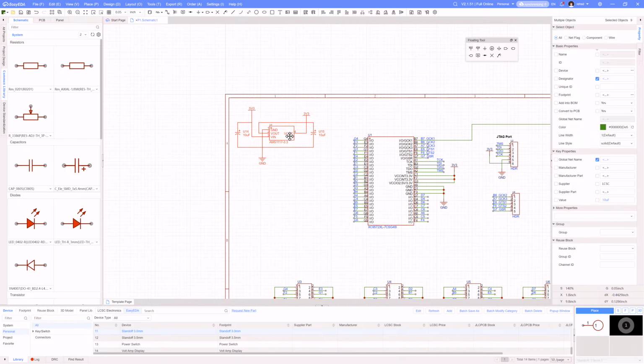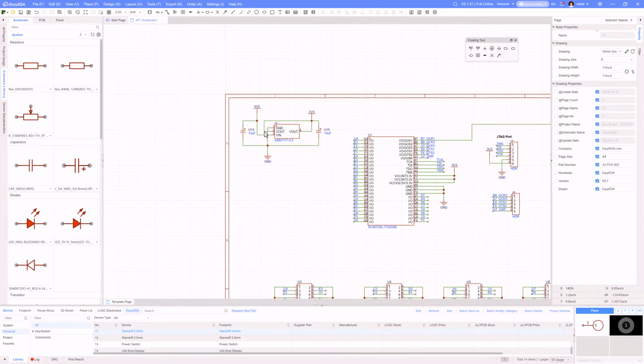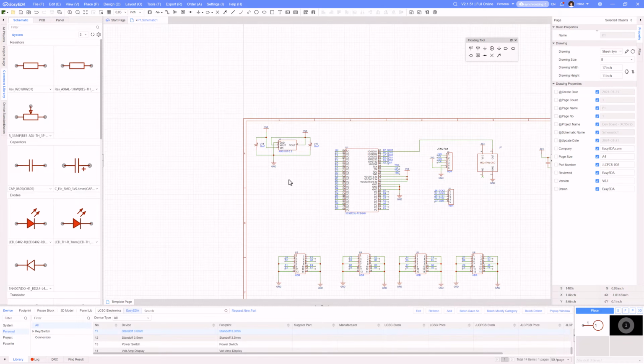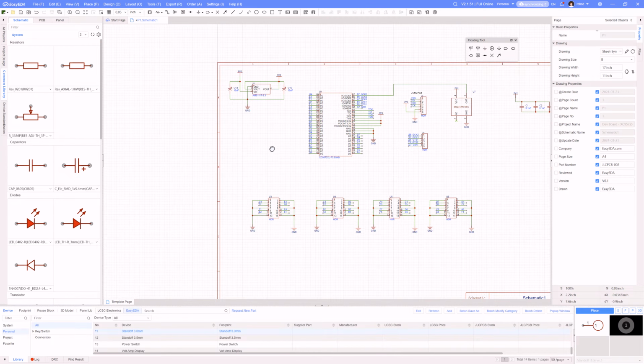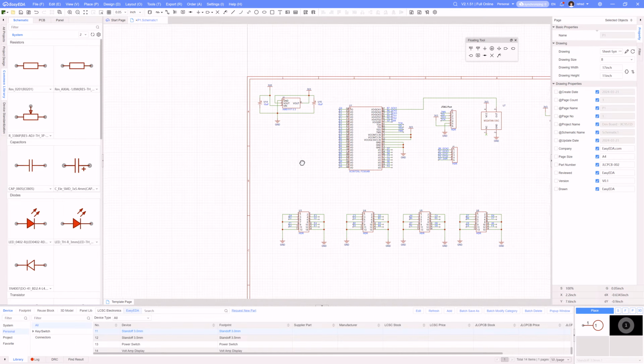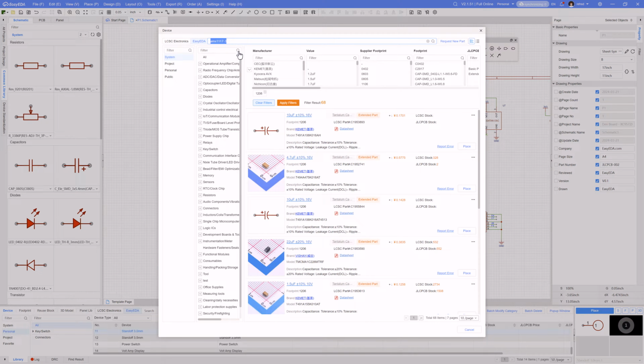Okay, so then I've got my 5 volt coming in to something. The question is, what is it going to come into? Do I want to go to a pin header, or do I want something a little bit better than that? And maybe for now, for simplicity, I'll just use a pin header. And so I'll bring 5 volt in on a pin header. I could do a barrel jack, I suppose. So that'd be something else.